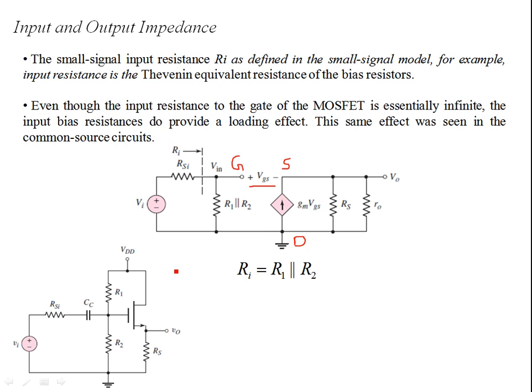This circuit can be derived from the common drain or source follower configuration, in which you see the drain over here, and this consists of the DC sources as well. When drawing an AC equivalent circuit, you usually kill the DC sources, so the drain is the common signal ground. Once this is grounded, and this is your gate terminal, your biasing resistances R1 and R2 appear as parallel resistances. The parallel combination of them constitutes the input resistance.